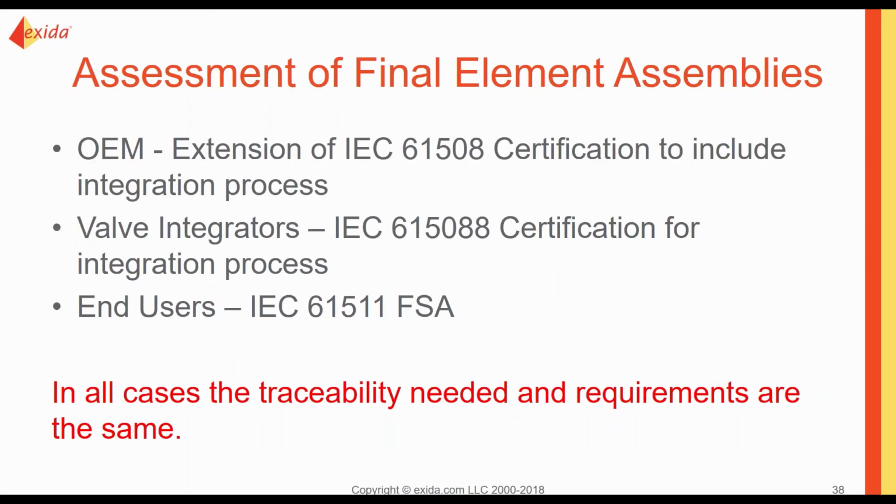For OEMs, typically that's an extension of a 61508 certification. They'll often have one for their devices, and then adding that integration process in there, ensuring that they're doing the right steps would be the way to do it. For a valve integrator, it'd be a 61508 certification as well. As an end user, they're not going to be certified, but it's going to be an assessment. It'll be a 61511 assessment. In all cases, exida would look for the exact same thing, whether it was under 508 or 511.